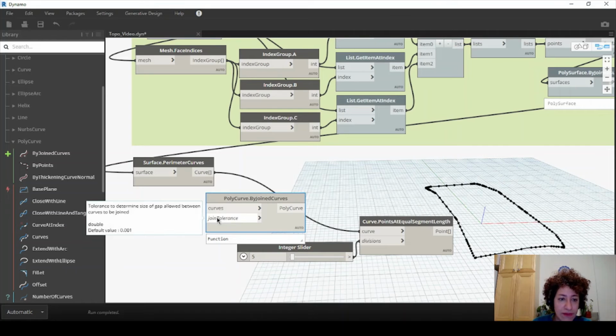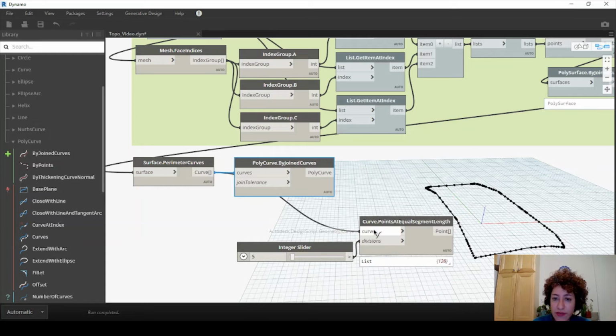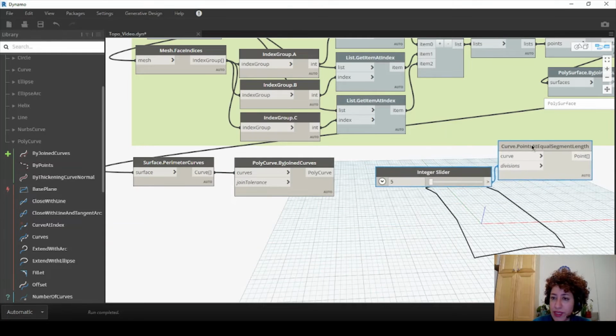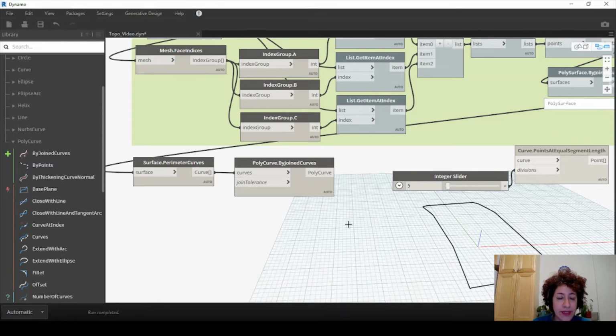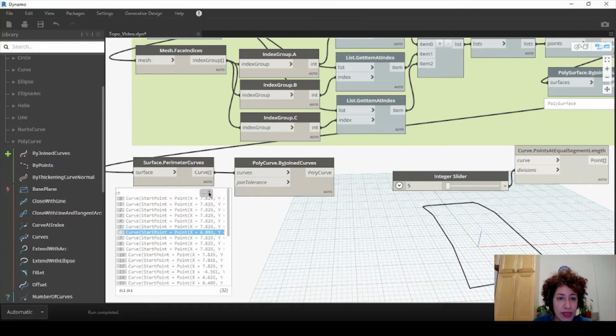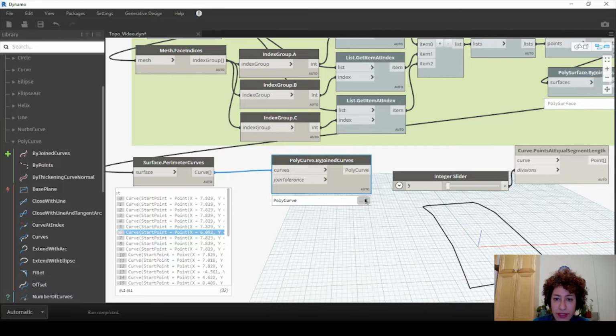And we have a join tolerance. I want to connect this one to this one. For now, let me move this to the end. And how about I pin this item and pin this item? So now you see we have 32 little lines, and we have 32 lines here because the tolerance is only 1 millimeter, 0.001.